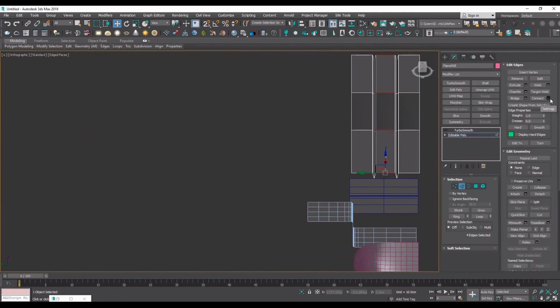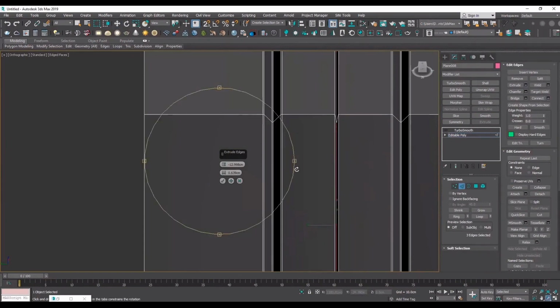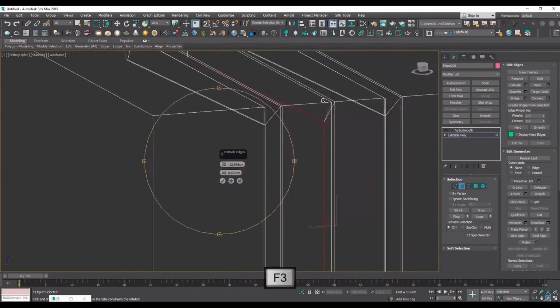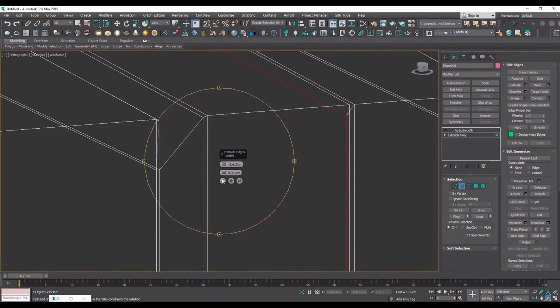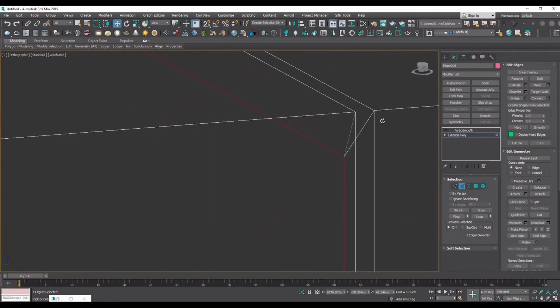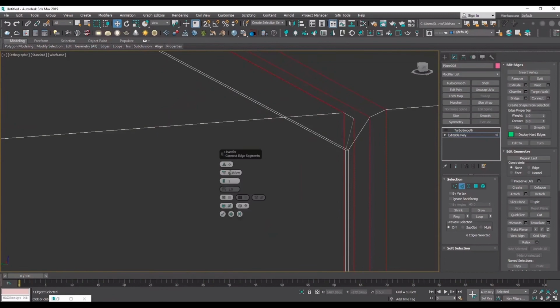So I was saying, when you want to just create a little hole on the surface, you can just do the extrusion instead of chamfer. But whenever you want the surface to go straight down, you need to first chamfer the main edge and then extrude it. One thing to keep in mind when you want to extrude something down in the exact orientation of the model is that you have to set the constraint to local mode to get it right.